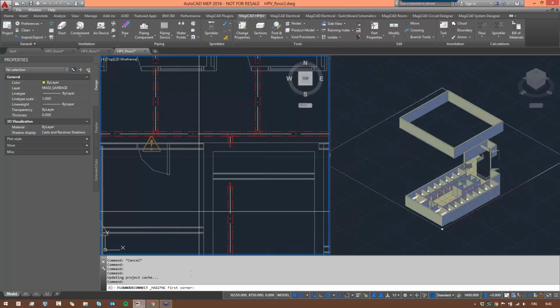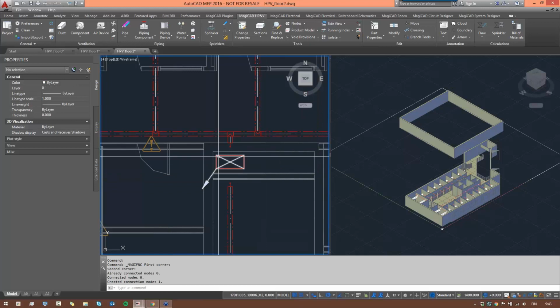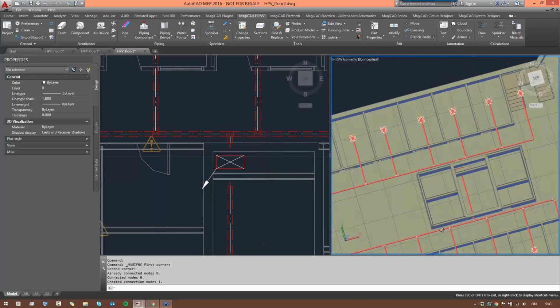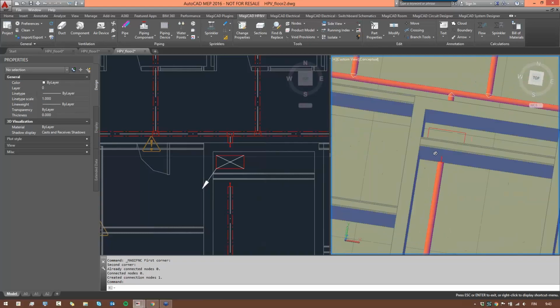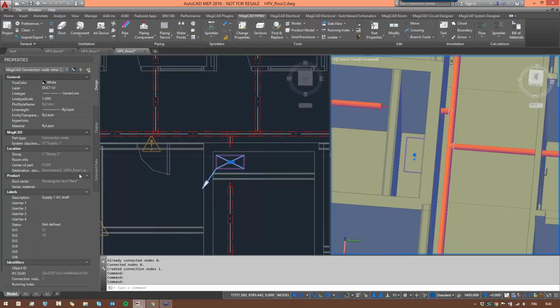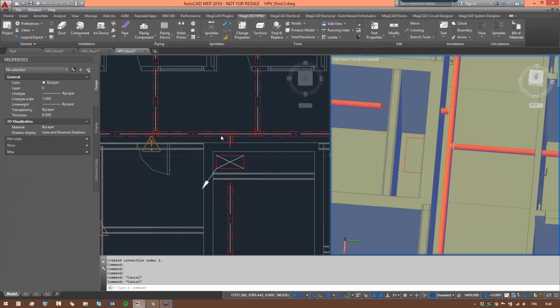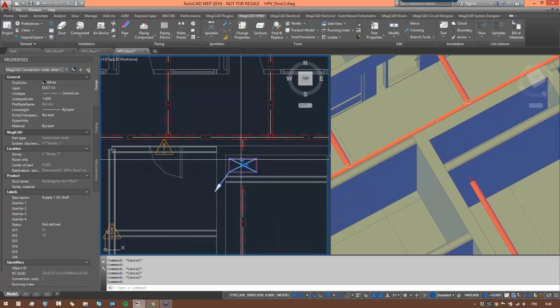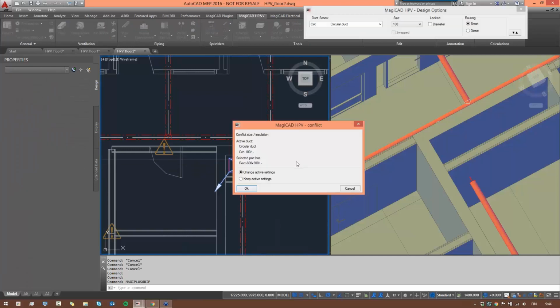Okay, as I selected the area option, I'm just going to make sure that it's inside that AC shaft. There it is. Connection arrow downwards, and as you can see now that I twisted the 3D, there it is at the bottom there. And when I select that one, center part on height level 0. Of course, on this floor, it's on height level 0. So let's draw from that one. We can normally start drawing from this one.